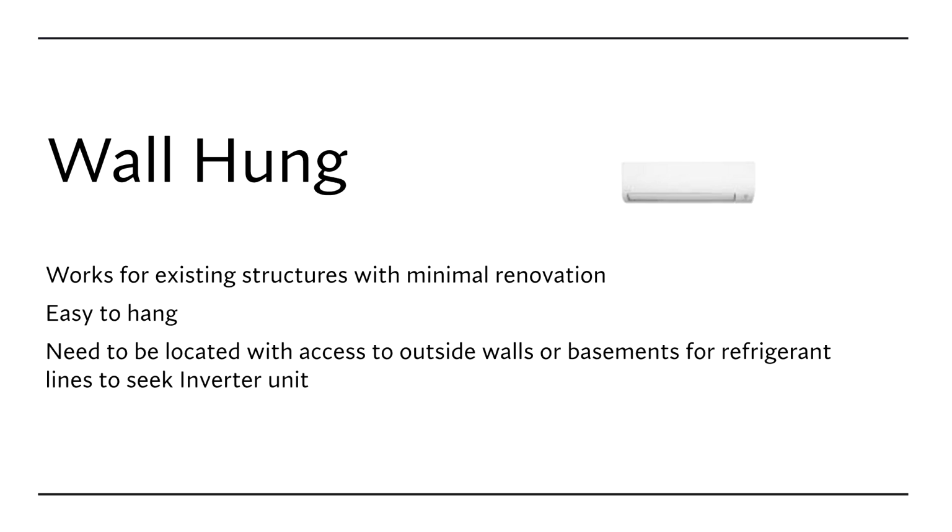So the reason these are designed this way is it's minimal intrusion into your space, and it only requires a 1.5-inch hole that the inverter covers up, and they run the line set and the communication cable back down through to get it to the outdoor unit. And then they should, if they do this right, seal up all the air gaps between any penetrations they've made through a wall, because again, we want to keep the house air sealed as much as we can.